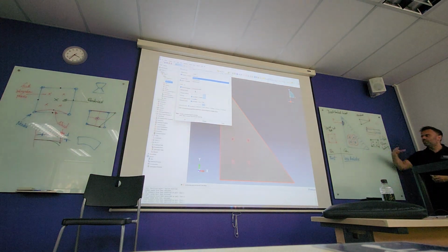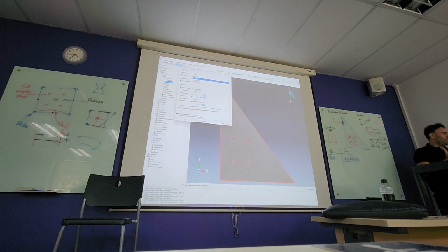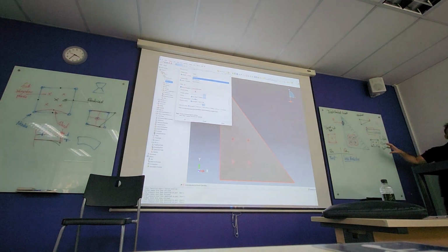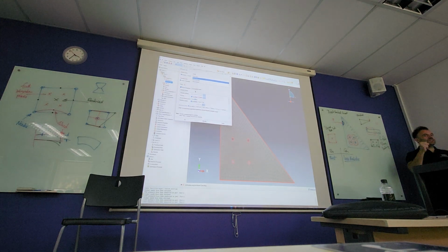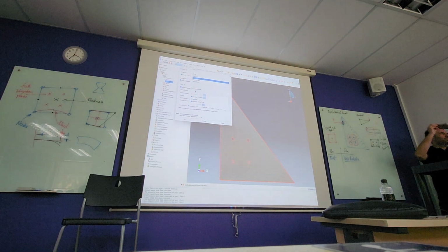What happens, just a bit more theory, but again, you're watching the video, is elements are stiffer than they should be. Yeah? So the results that these elements report tell you the structure is stiffer than reality shows. For example, in reality, if I put 1 Newton on this book, it will bend.